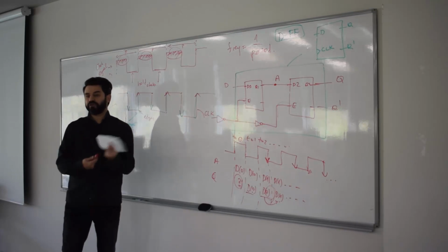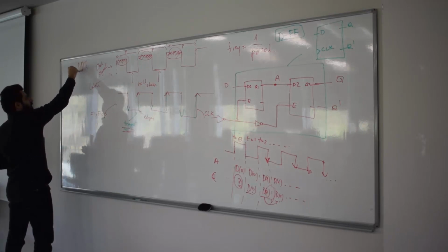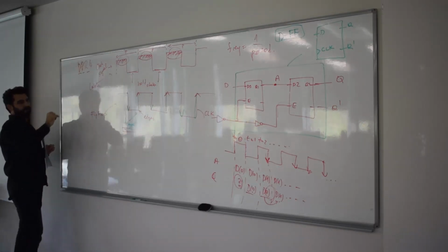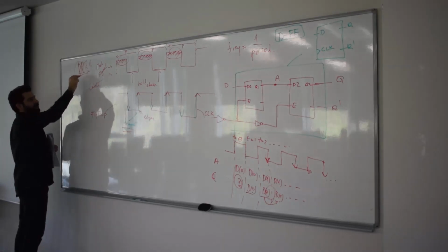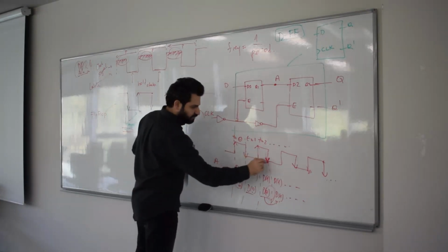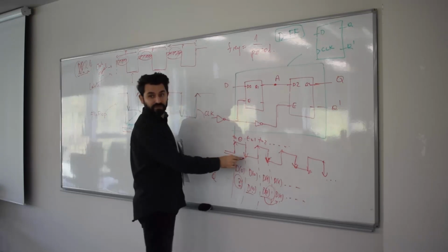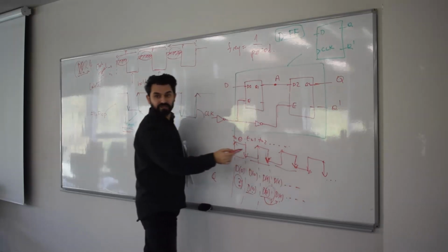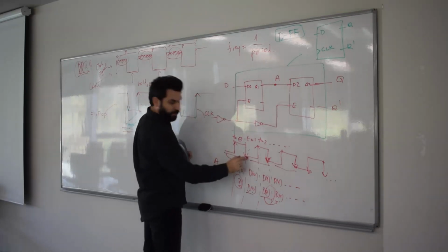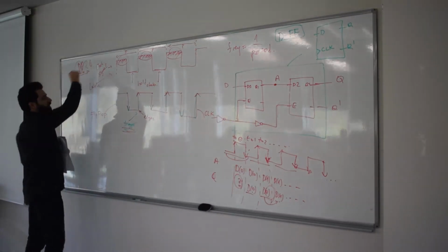You may have heard from, for example, RAM technology, DDR. Have you heard that? This is double data rate. Actually, DDR4, right? Double data rate. What is double data rate? Well, double data rate is this. Rising edge, falling edge. Rising edge, falling edge. Conventionally, we have either a falling edge or rising edge. But now, these circuits have both rising edge and falling edge, doubling the transfer rate. Okay? That's why people call it double data rate.